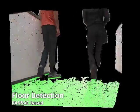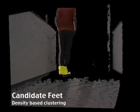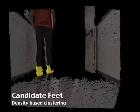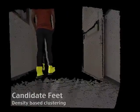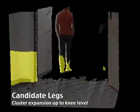The floor is found as the most prominent horizontal plane. All 3D points lying within 20 centimeters of the floor are clustered together, and clusters matching the approximate dimensions of feet are expanded upwards and retained as candidate legs. In fact, many such candidates are not legs.